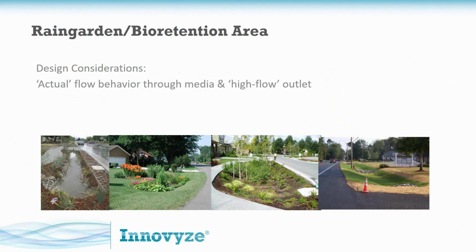I mentioned the sand might get washed away, so there needs to be a diversion, with even the 2-year rainfall event needing to be diverted so that it doesn't wash through this facility, okay? Well, I have firsthand seen this a number of times and gotten calls myself from people out in the field. It's not a very pleasant phone call when the first rainfall event, right, these facilities are washed out. You don't want to get that call.